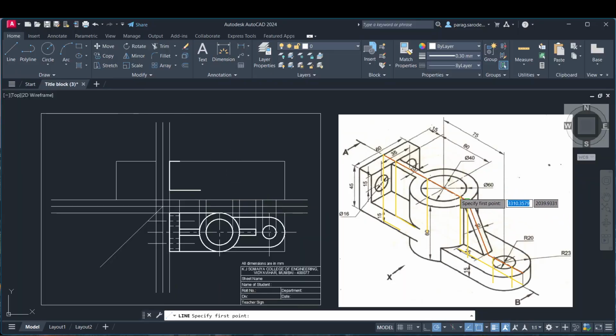Now once we cut this, we can see that the inner portions of the cylinder will be completely visible. So let us take these portions in this way. So we can say that these are the two boundaries which will be visible for the whole figure, and even after cutting, this top boundary of the figure will be visible. So we can extend it till this edge, let us extend it till the outside edge. So from this corner, or we can say the edge of the sectional front view, till this edge of the cylinder, we have drawn a line by taking this line as a reference. Okay, we can see that in this way, right?